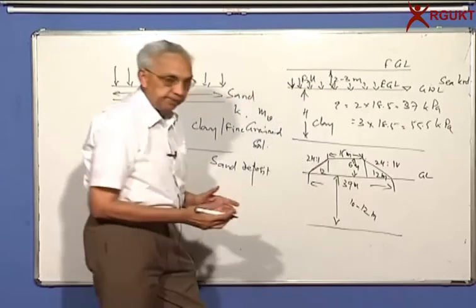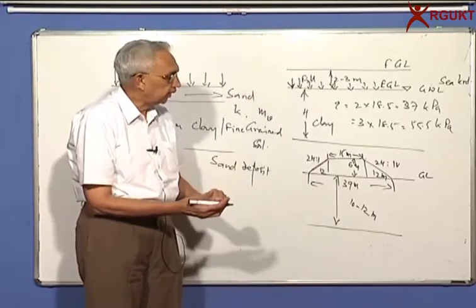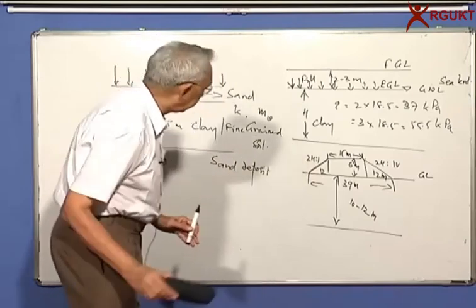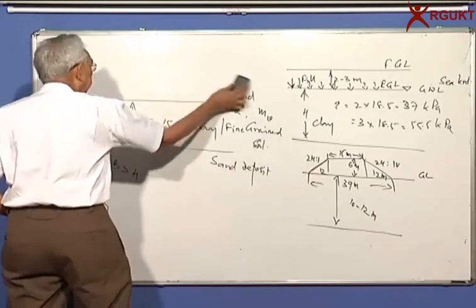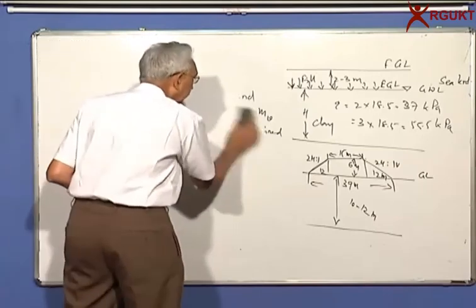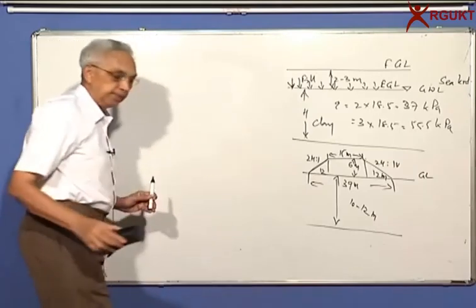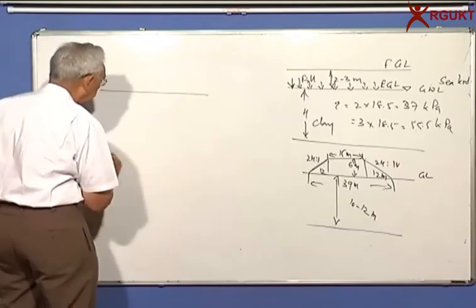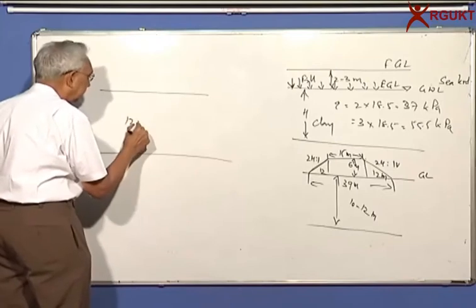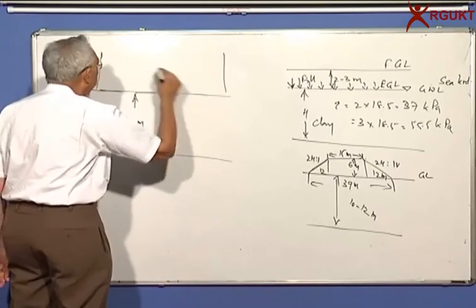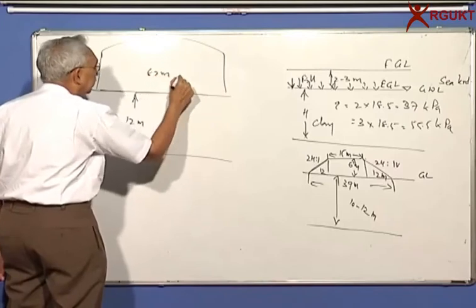You can again see the thickness is smaller than the width of the loaded area. Or you also look at some of these liquid storage tanks by Indian Oil or Bharat Petroleum. The largest one is in Hazira, where I have a soft clay about 12 meters thick, and they have constructed a liquid storage tank which is 82 meters in diameter.